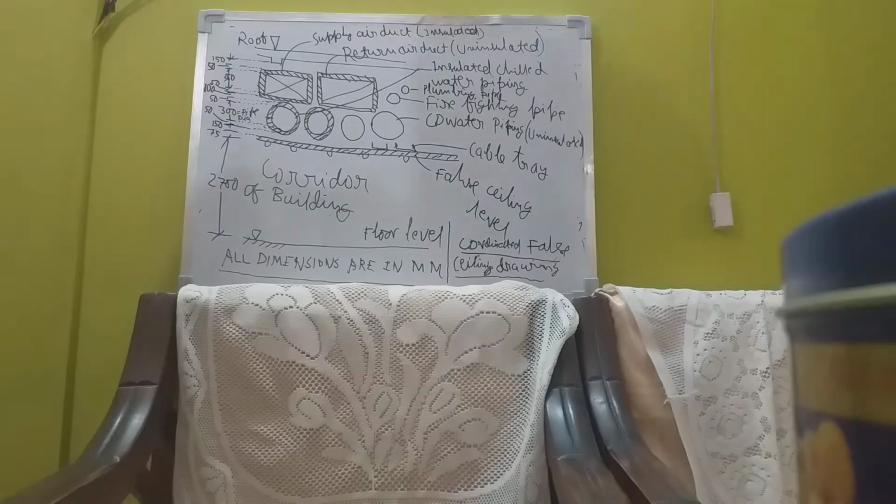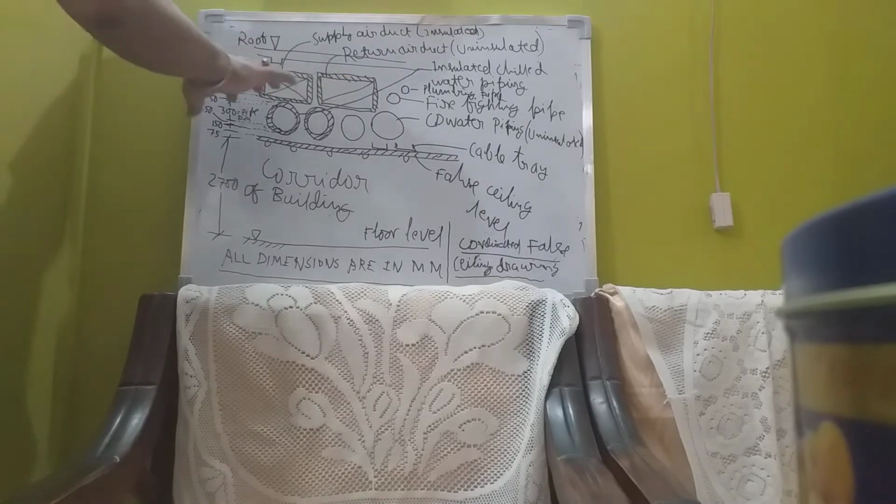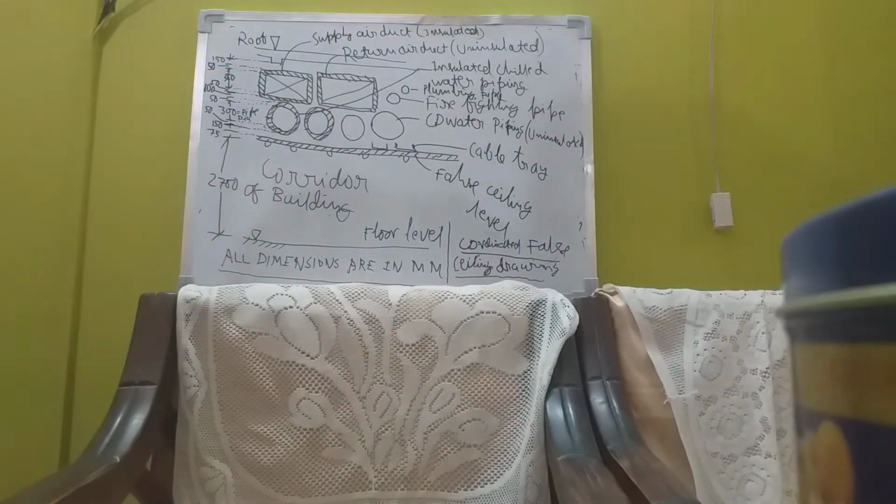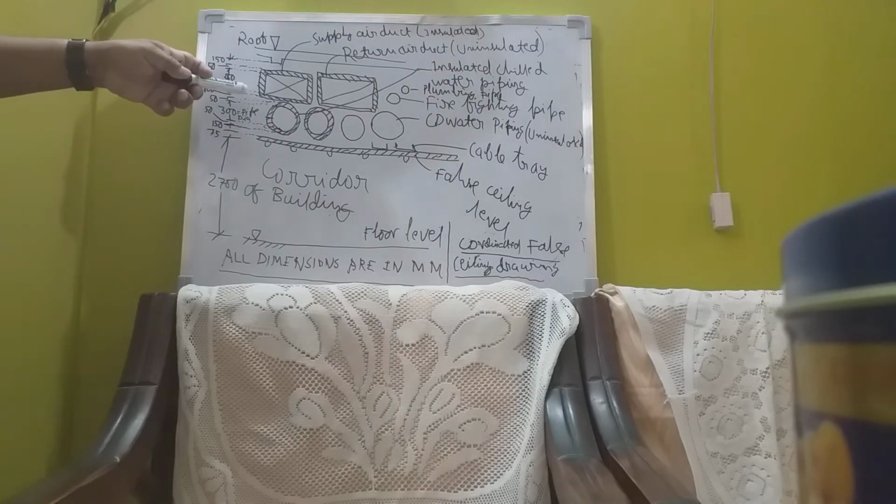Why 100 mm? So that you can put your hand inside, do the maintenance work and put these things in place. You need a 100 mm gap here to do proper maintenance work. Remember, this is 100 mm. Just see very minutely, this is 100 mm. Why?